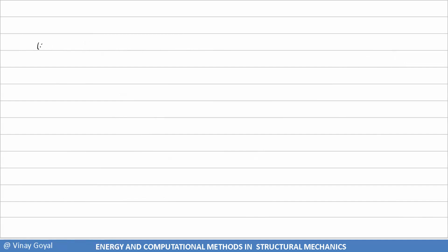So in terms of deflections alone, step 7, I have N of x1 equals the double integral, not triple integral, sorry about that, over the cross-sectional area A of sigma 1 dA. And for a one-dimensional bar, clearly, I get E times epsilon 1 dA. And notice how epsilon 1 is u1 prime.